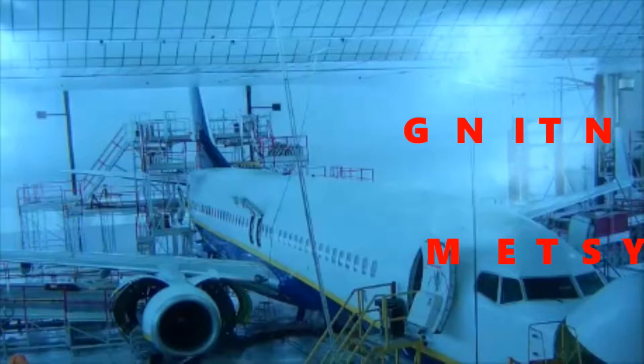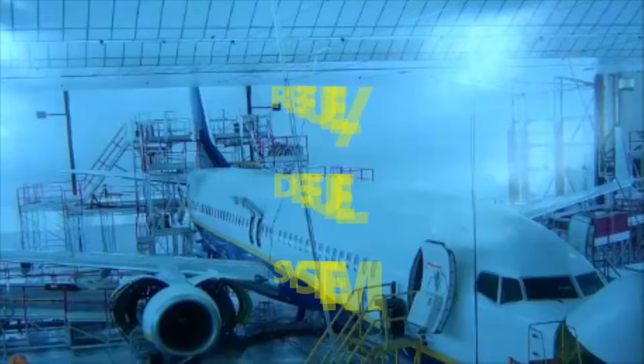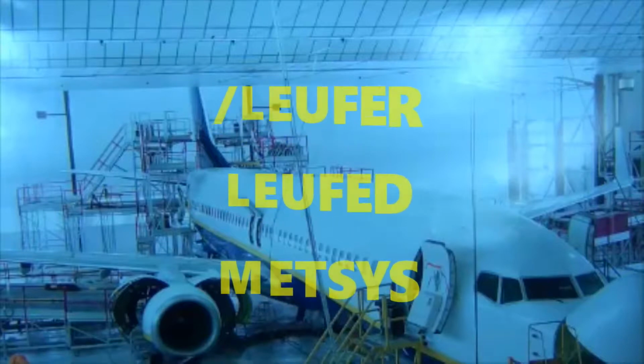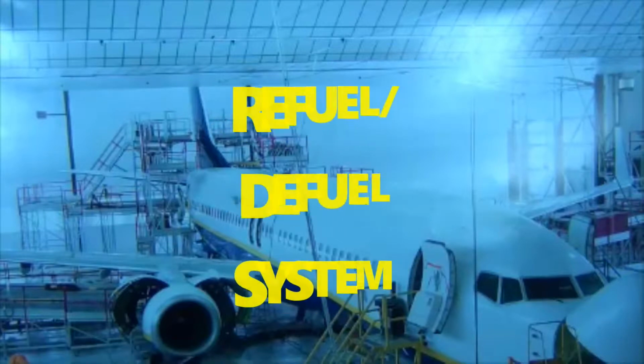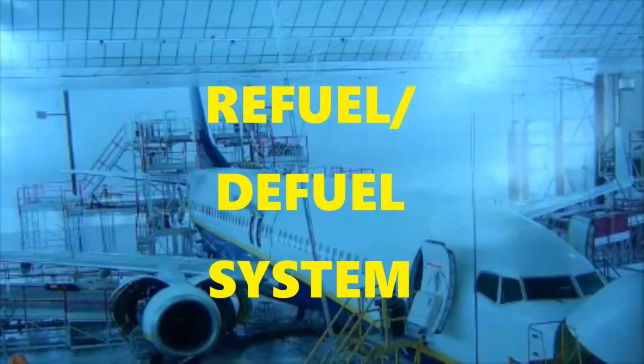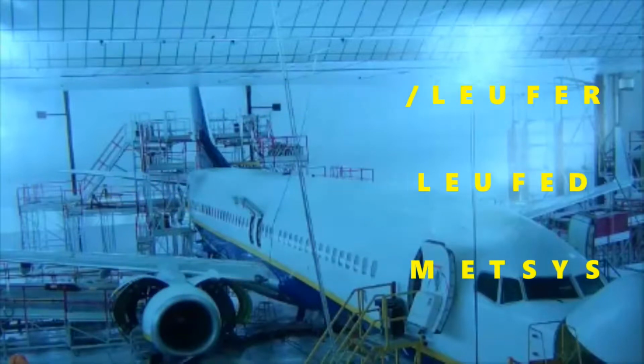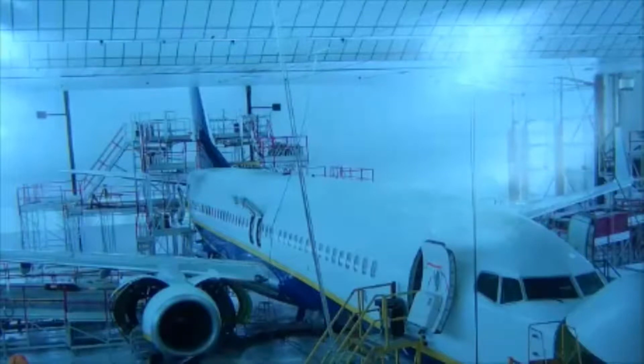You also have a refuel defuel system. The refueling defueling system is controlling that flow of fuel. So that's the aspect of the fuel system where we're talking about controlling the flow of fuel going into or out of the aircraft. There is a control panel for that, and there's a pre-selector. Just follow the procedures on how to refuel. And then you also, of course, remember I mentioned quantity, temperature, and pressure.